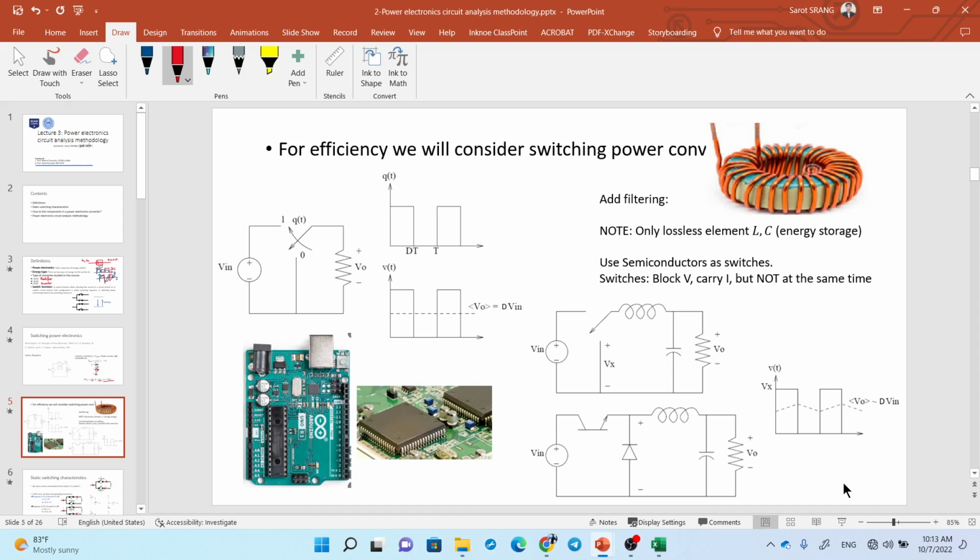So you're going to see the switching function. For example, say you have an input voltage here, and you want to reduce the voltage at the output by half. Then you just need to switch like this: switch to give full voltage 50% of the time, and then switch to supply zero voltage 50% of the time. That means you only release 50% of the power to there.